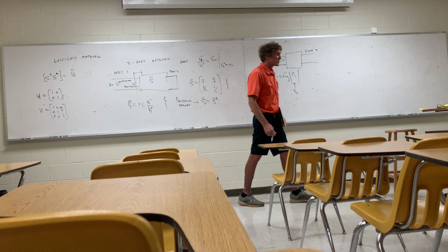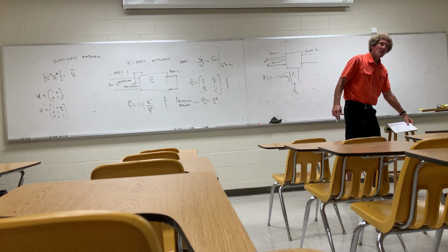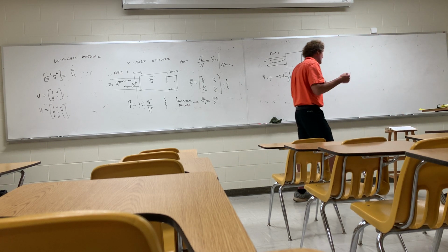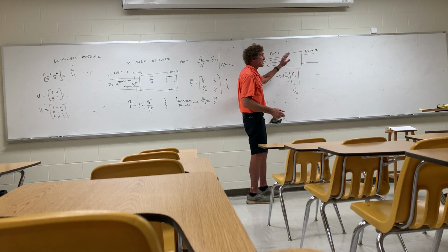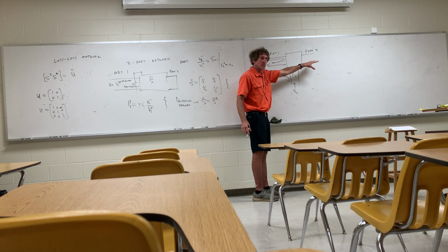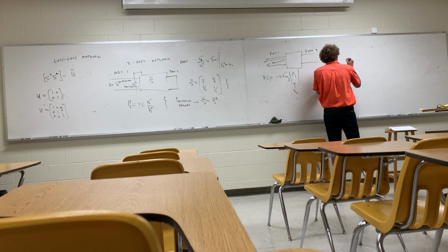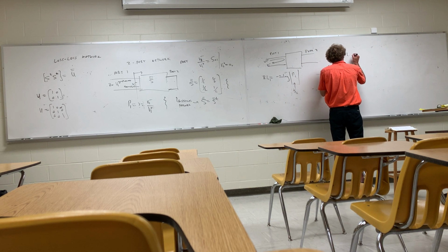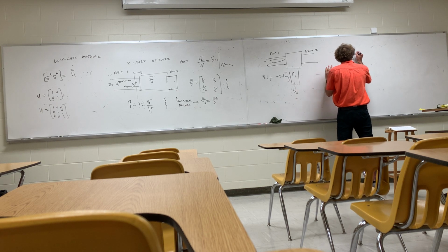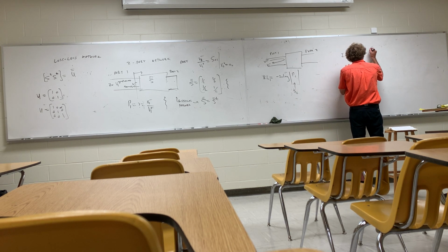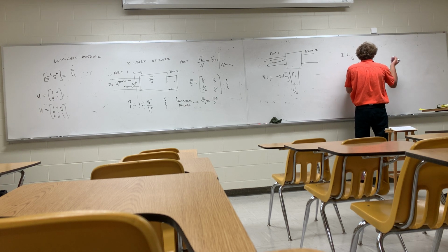Now, when they talk about insertion loss, what you're always thinking about is if I put a signal in port 1, how much of that signal gets out on port 2. Do y'all follow me? So, insertion loss, or IL, and they'll have i comma j here. That's really minus 20 times the log of the magnitude of S, and this would be i comma j. Let me explain to you.